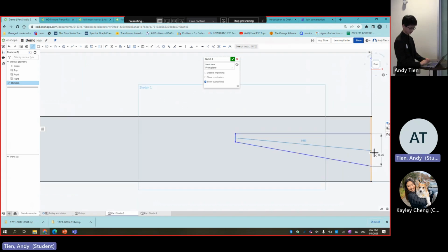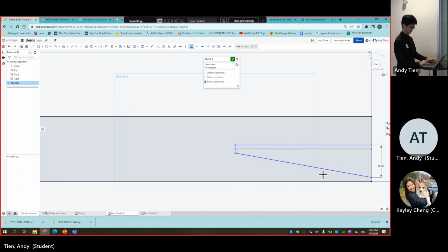So what I'm going to first do is get the midpoint, right? And then once I get the midpoint, I can define this line to be perpendicular to that line. So this just perpendicularly bisects my shape, and that ensures that I have a trapezoid. So if you look over here, I have perpendicular. And there you go. And then if I remove this define.